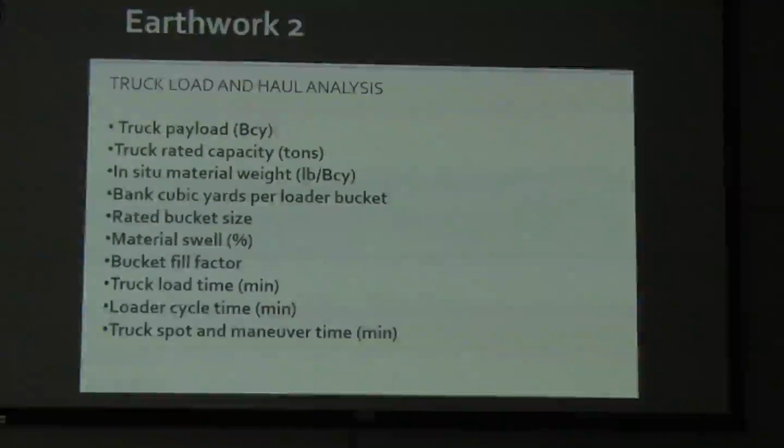Truck load and haul analysis. It's based on the truck payload in bank cubic yards, or the truck rated capacity in tons, or its equivalent in cubic yards. Based on weight, in situ material weight in pounds per bank cubic yard, the bank cubic yards per loader bucket, rated bucket size, the material swell, the bucket fill factor, the truck load time in minutes, the loader cycle time in minutes, and then the truck spot and maneuver time in minutes.